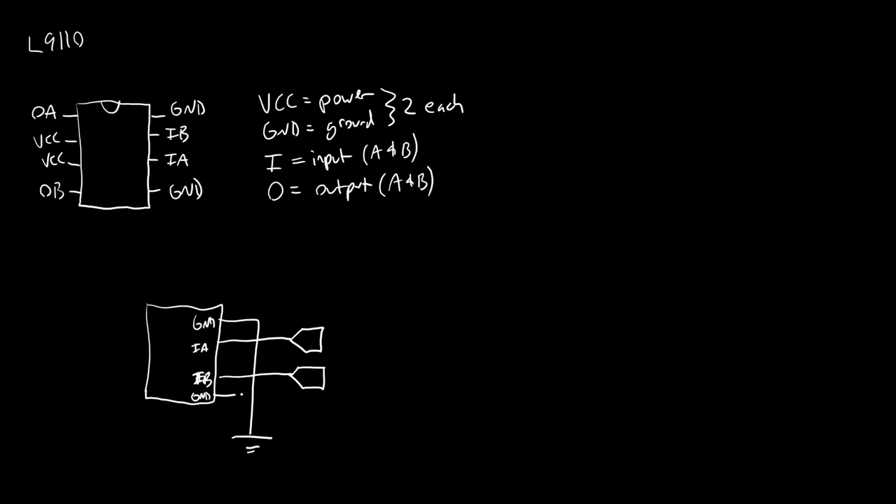Now, this is something that confuses some students the first time they see this datasheet. Way back in an earlier video somewhere in the series, I think I talked about different conventions for representing when wires connect or when they cross each other. In this specific datasheet, they are using the convention that a dot means a connection, and crossing like this just means the wires cross. There might be other datasheets or diagrams where they'll draw a little loop or bridge like that to indicate that those 2 wires are not connected there.